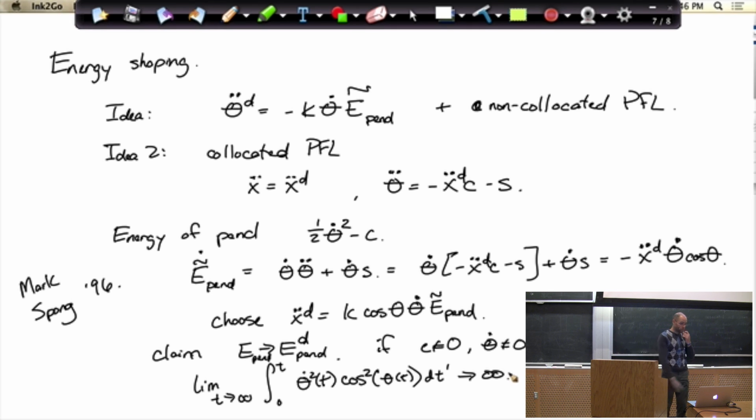Even if you have unknown parameters of your robot arm, for instance, and you have a desired trajectory, you can adapt the parameters, my estimate of the parameters and the controller at the same time, and guarantee that I'm going to get to my desired trajectory. It's only for fully actuated robots, but a hugely powerful result from adaptive control.